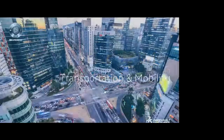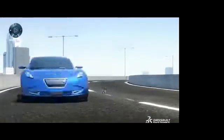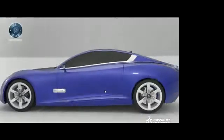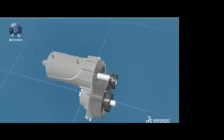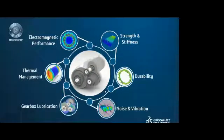Change with electric, autonomous, and connected mobility. Electric drive systems play a key role in battery electric vehicles. The primary challenge in electric drive engineering is achieving a high power density. This means packing high power in a small space that must contain the electric machine, a gearbox, the housing, and often the power electronics unit, integrated or closely attached, all at a reasonable cost. These electric drive systems are complex, and their performance needs to be optimized across multiple competing disciplines, including electromagnetic performance, thermal management, gearbox lubrication, noise and vibration, durability, strength, and stiffness.